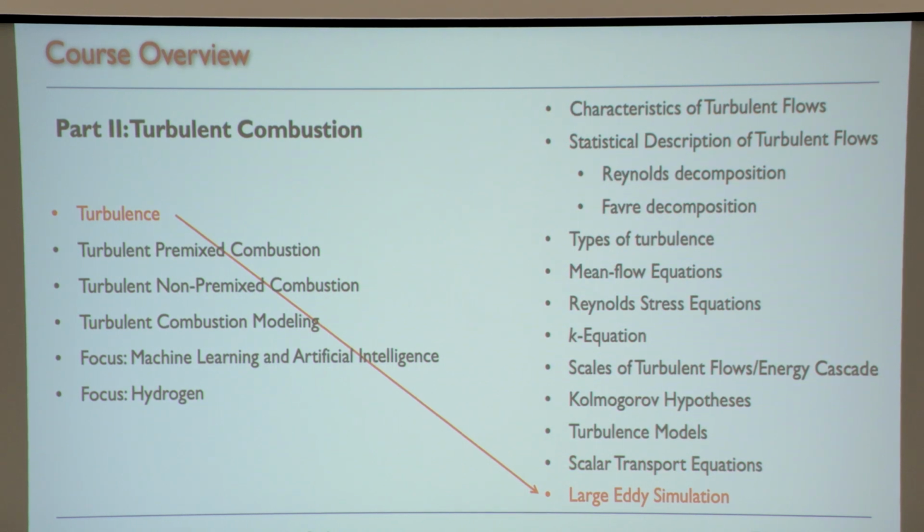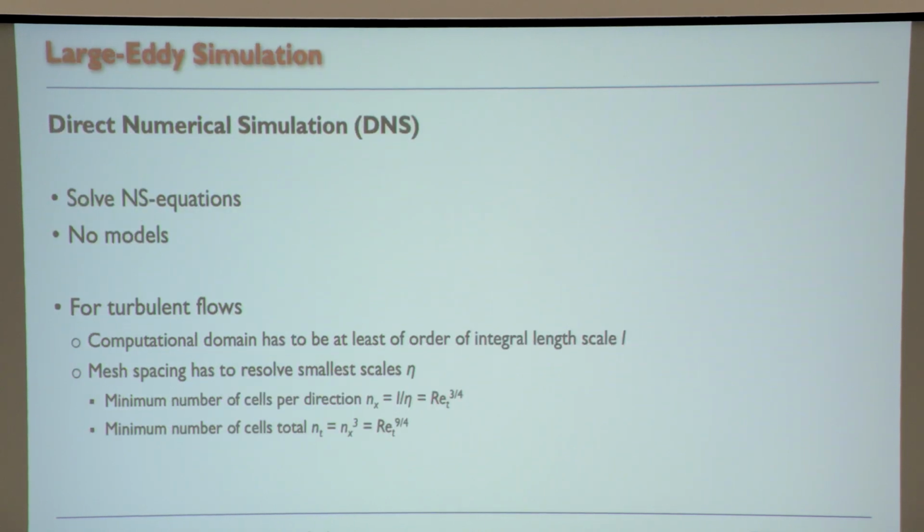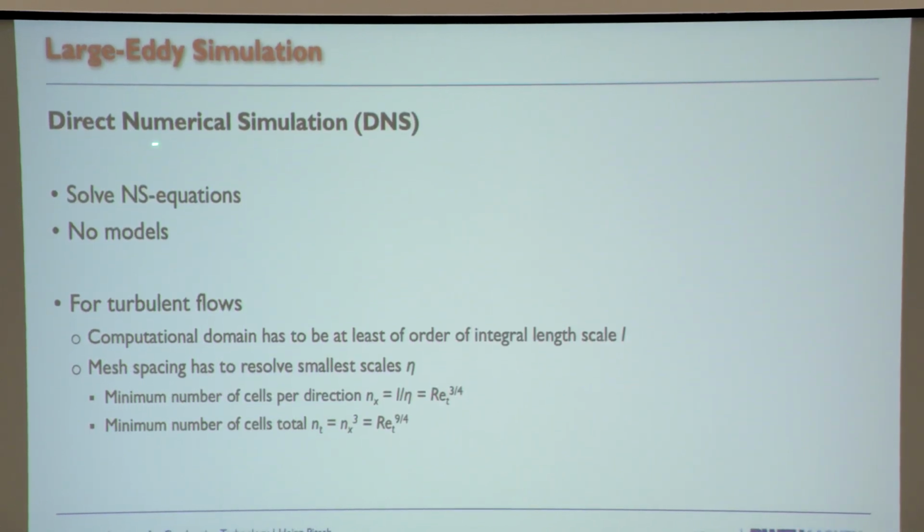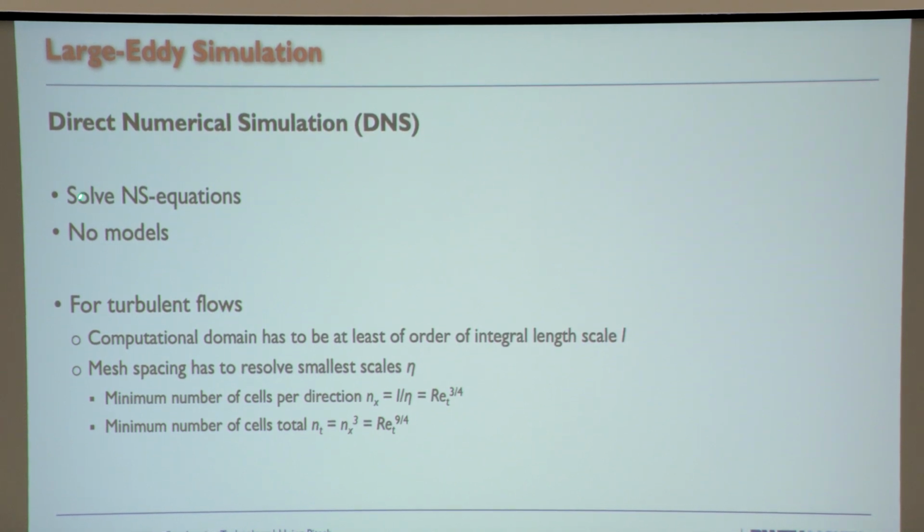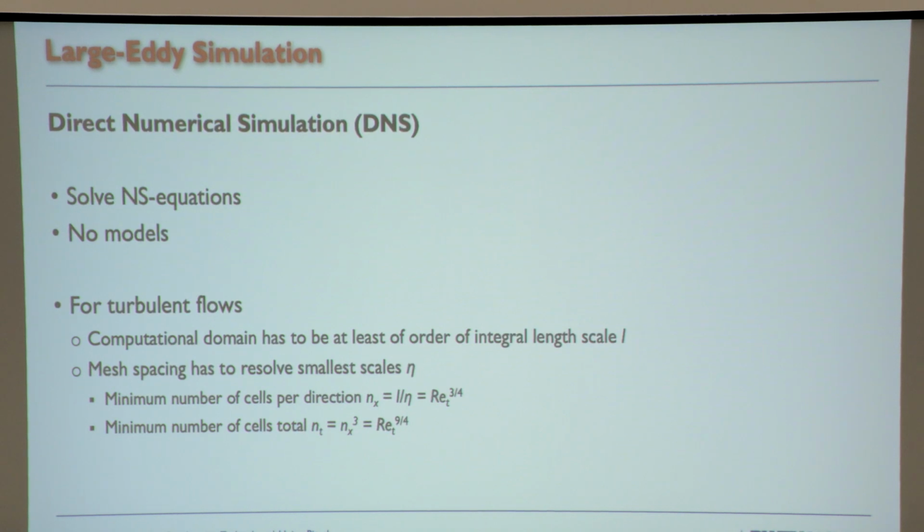Now for large eddy simulation, I have a section here, and we're a little bit behind, so I'll try to go through this quickly and maybe just give you the general idea of what large eddy simulations are. So direct numerical simulation, I mentioned this already. We solve the Navier-Stokes equations without any models, augmented by the scalar equations we need. Everything is closed in these equations, and we need no models.